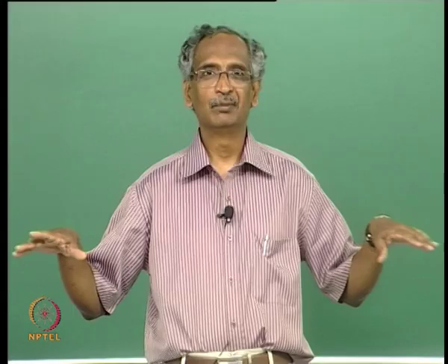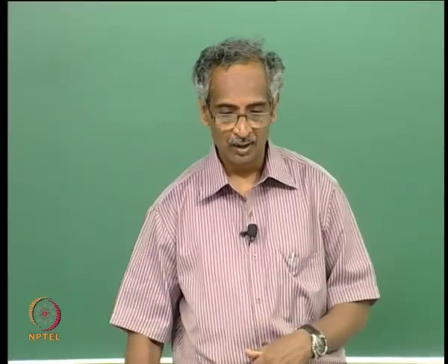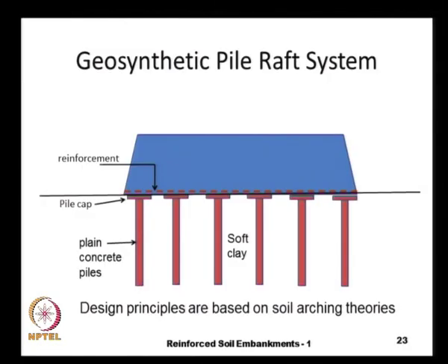Here our slab that we construct does not have any bending stiffness, because it is all made up of flexible materials, and then the design itself is based on the arching theories that we will see later on. This concept of the geosynthetic pile raft system has successfully been used at several places, and it is found to be very fast and also very economical compared to so many other alternatives.